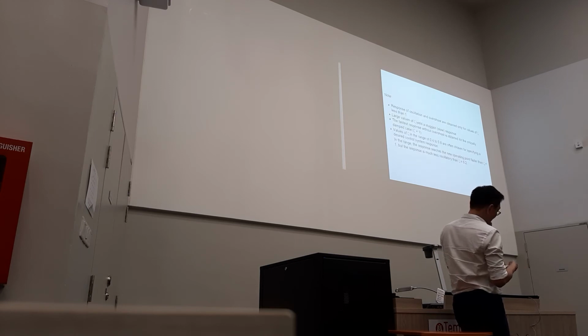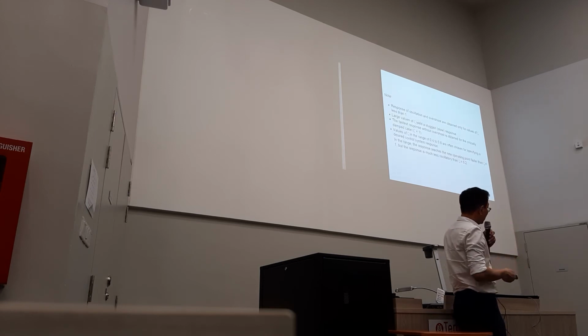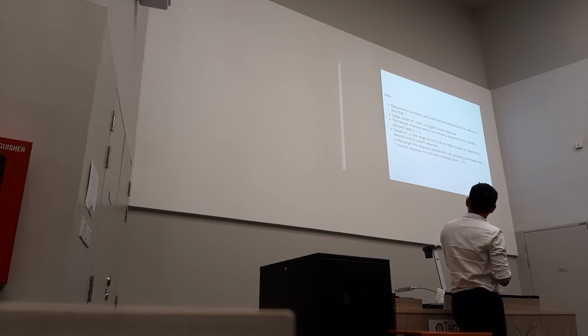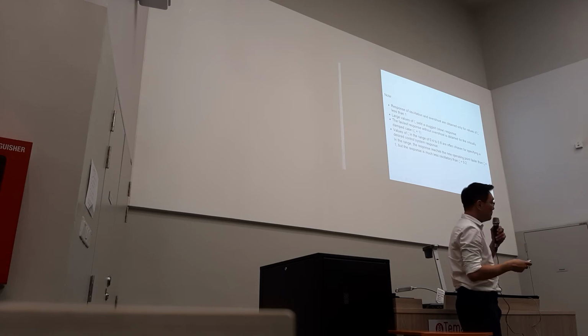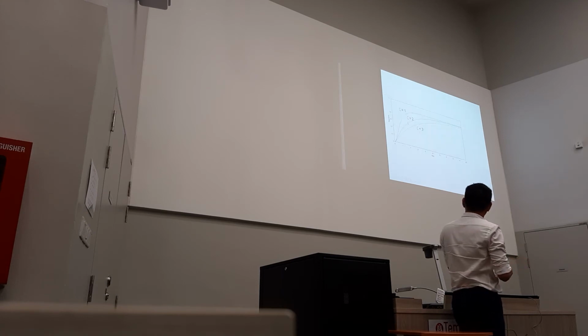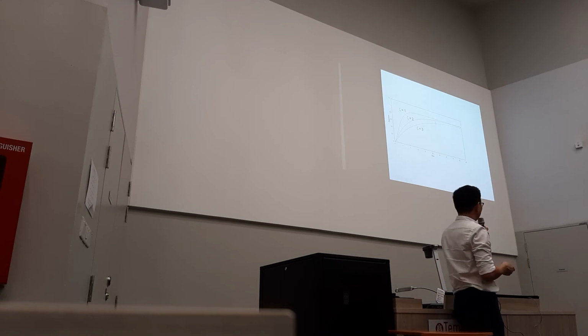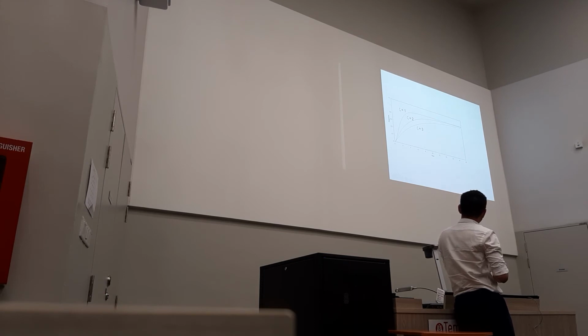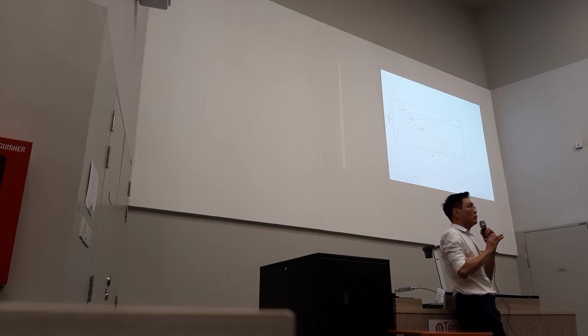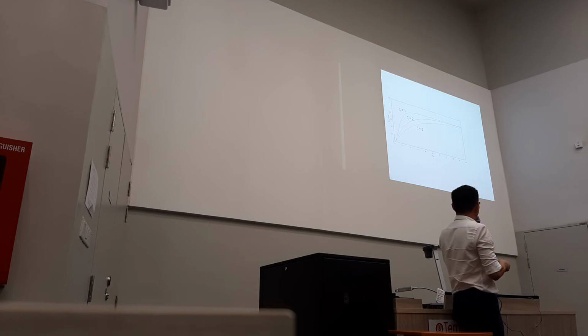We look at this one. I will read this one and then go back to the previous slide. So if you look at this, the oscillating response and overshoot are obtained only for values of zeta less than 1. Remember, for more than 1, my system did not oscillate. It just goes back to the value that I want. So with a damping coefficient more than 1, no oscillation; I disturb the system, it will slowly reach the final output.